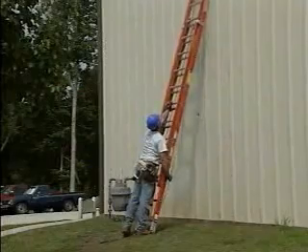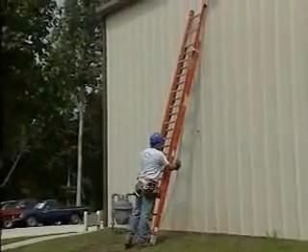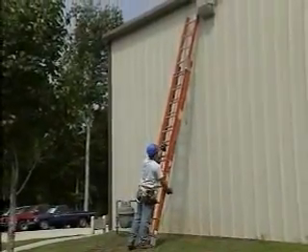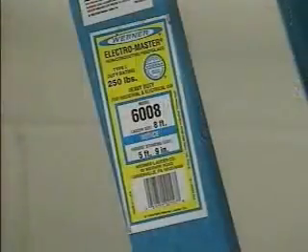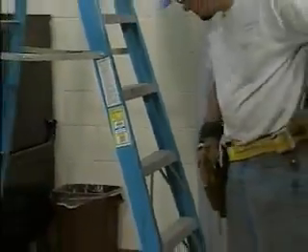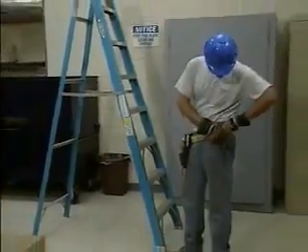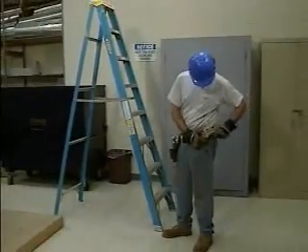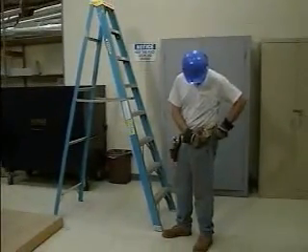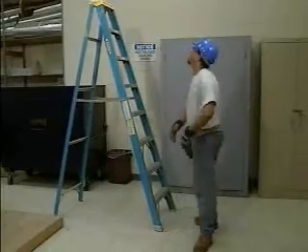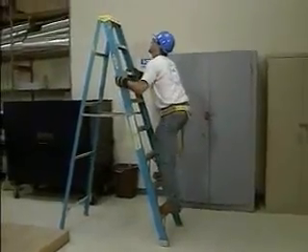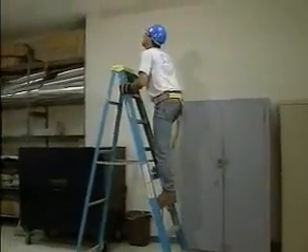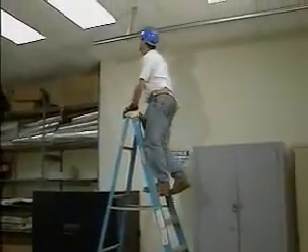Often, determining the kind of ladder to use depends on whether the ladder will be leaned against a structure or if it needs to be freestanding. Determining how much weight the ladder will need to support is also important. Ladders are rated to support different amounts of weight, so you have to know the total amount of weight that the ladder will need to bear, which includes the weight of the person climbing the ladder, plus the weight of any tools and supplies that the person might be carrying.